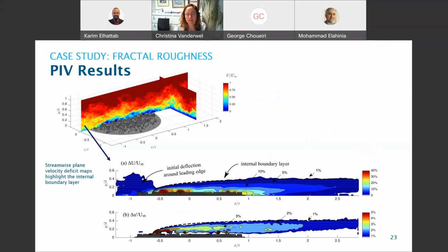This is the velocity defect, or the velocity deficit map, that's created by the presence of that city. And so this city is actually slowing down the flow locally, and that's the net drag, the effect of the city there.